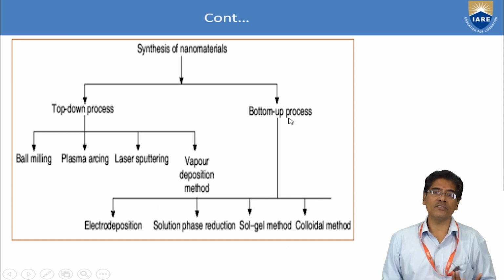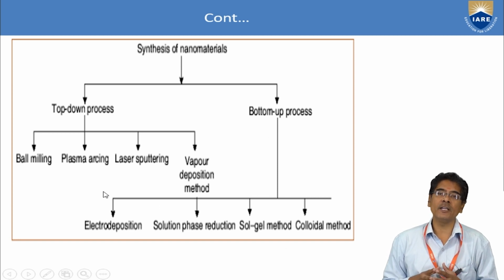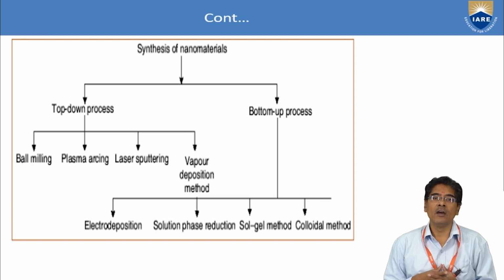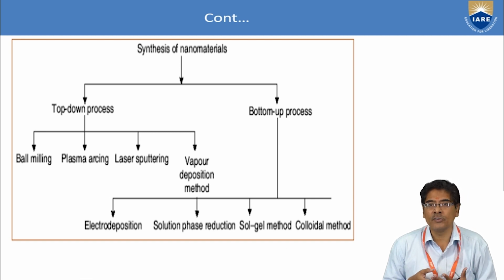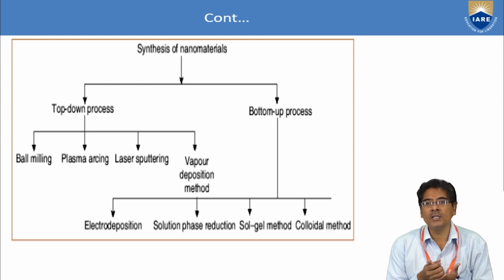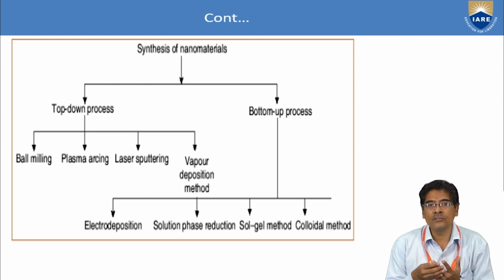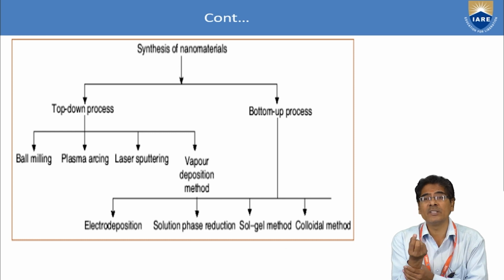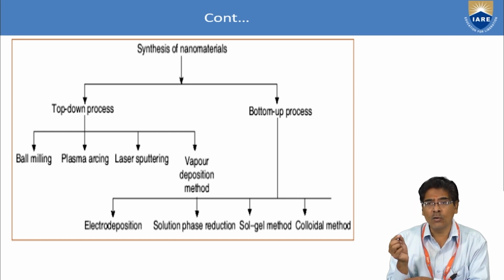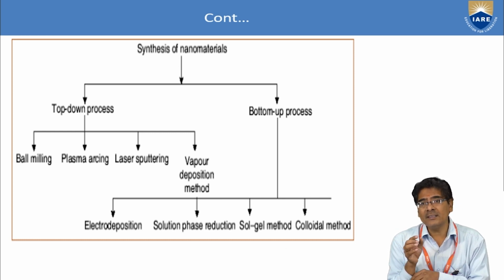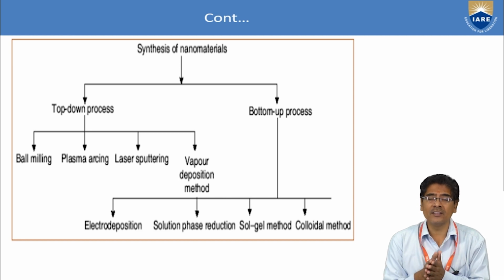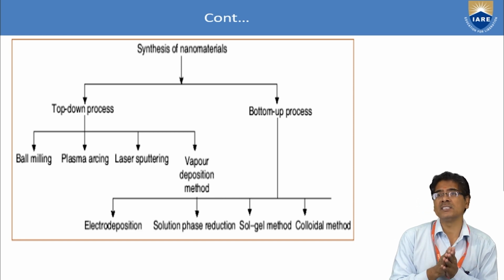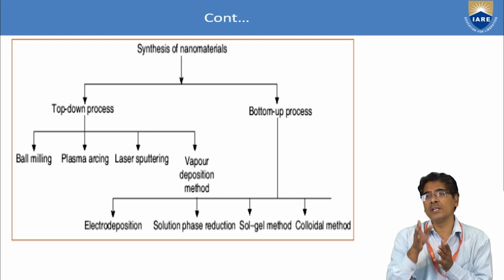So the bottom-up process can be fabricated by different fabrication techniques like electrodeposition, right? Electrodeposition and solution phase reduction, sol gel method, solution gel method, that is what we call the sol gel method, and colloidal method. So these are the fabrication methods which are included in the bottom-up process.